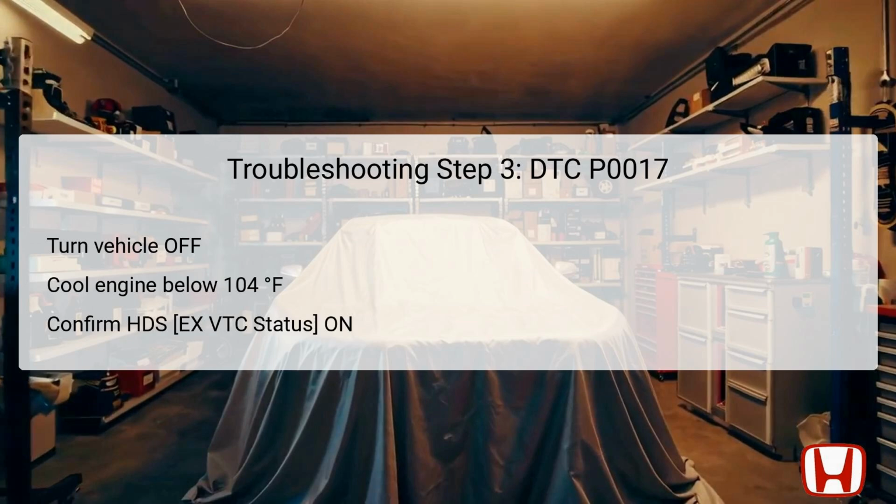The third step involves turning the vehicle back to the off mode and again allowing the engine to cool to below 104 degrees Fahrenheit, 40 degrees Celsius. Cooling is crucial for maintaining safe operating conditions during diagnostics. After the engine has cooled appropriately, restart the engine while monitoring the HDS system for the XVTC status. You need to ensure this status turns on, indicating that the valve timing system is effectively activated and functioning.